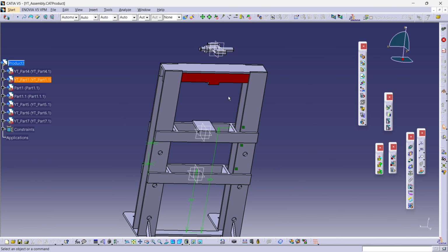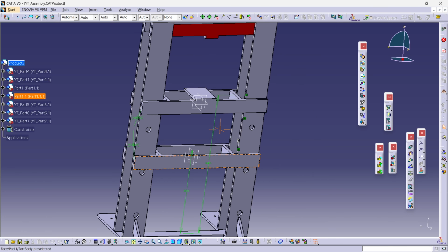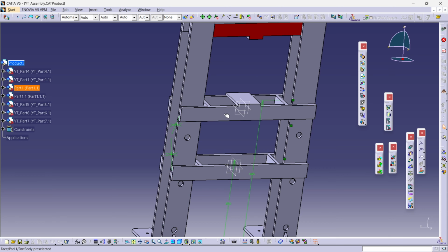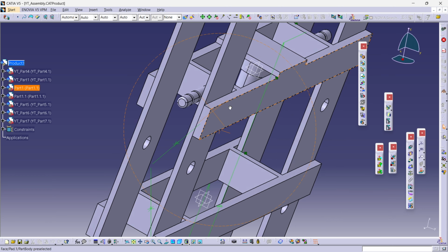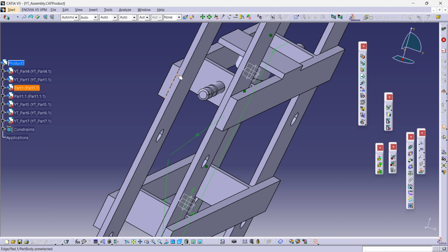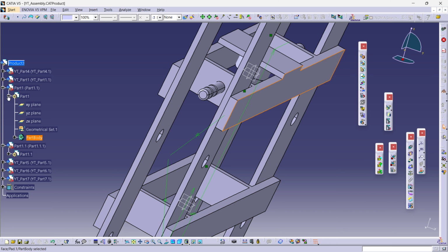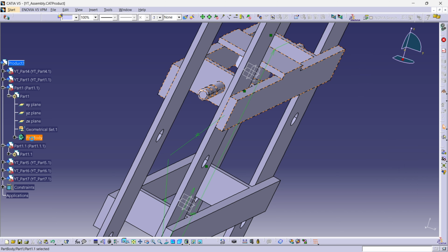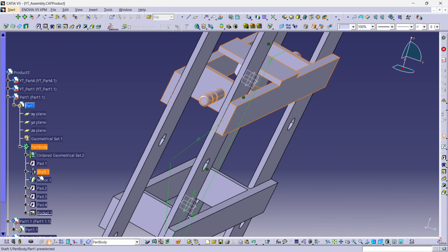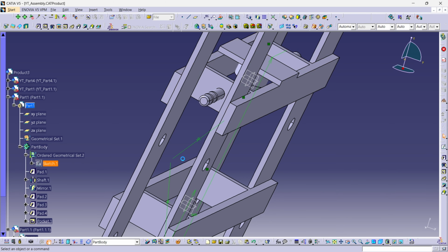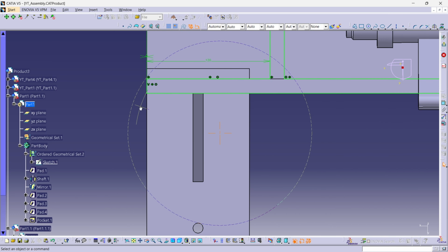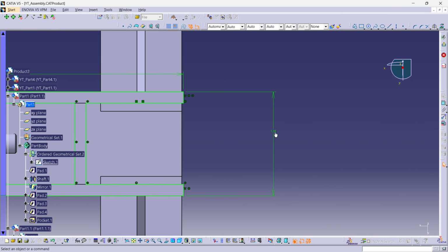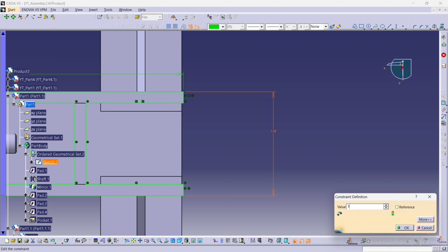For now, what I want you to do is first of all open this part design, because I'm sure there are some people who can see the gap between this. As I mentioned earlier, just go in your part design and update this sketch, make the width 128. I guess it is 140 in yours, so make sure it is 128.